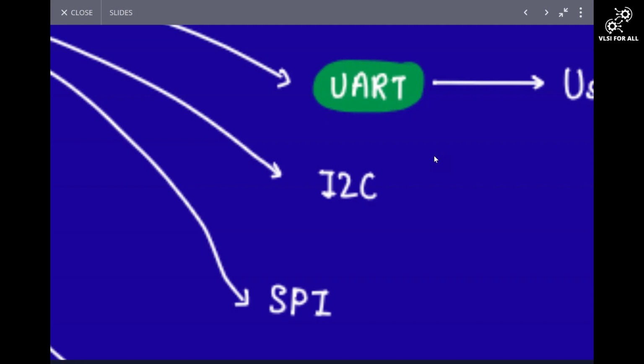So all your sensors that you have right now, let's say a thermostat. Thermostats use a temperature sensor. Let's say a common temperature sensor is LM75. That LM75 is running at a certain clock. Your processor is running at a certain clock, right? So when these two devices are running at different clocks, they cannot easily communicate, right? Without you designing some standard such that these two devices can communicate effectively, right?